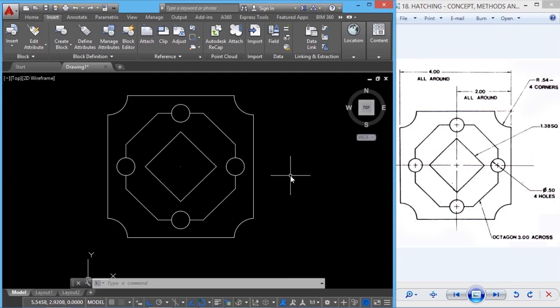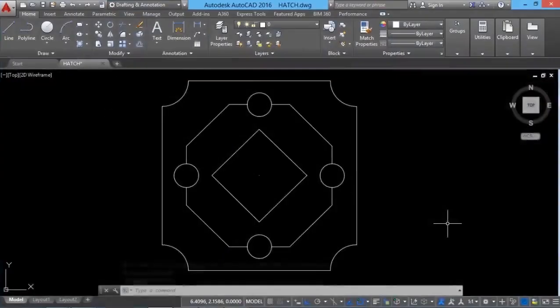Next, we will try the concept of hatching in this figure. Hatching in AutoCAD is also called pattern filling, because while you perform hatching, we fill certain predefined areas with predefined patterns. When you go through this figure, you can locate several areas. For example, we have an outermost area here, then we have this intermediate area followed by an innermost area, and we also have small areas within each circle. Using hatch command, we can fill in these areas with any desired patterns with suitable parameters and styles.